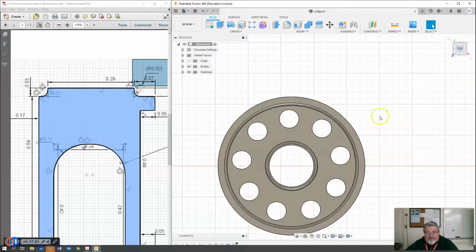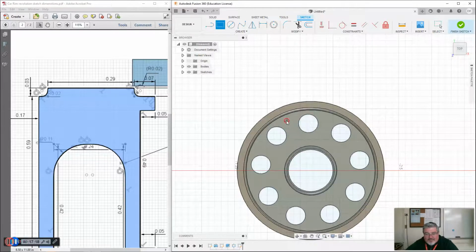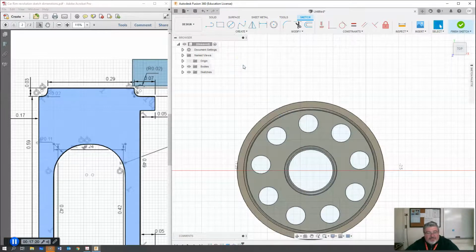Then once I have that, if I want to play around a little more, make it a little more unique, I can put another sketch. And this time, I'm just going to put a rectangle in between. Maybe I put a rectangle like this. Or maybe instead of a rectangle, hit escape, maybe I could do triangles this time. Let's do it. So once I have a rectangle drawn like that, I should be able to manipulate it.